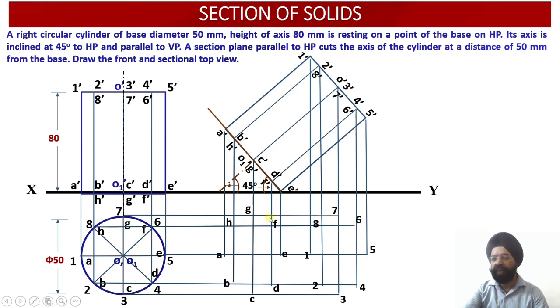So let me join. First of all, work out the two ellipses. As I have explained, since we are looking from the top, this ellipse, which corresponds to the top face, will be dark. And the ellipse I have obtained corresponding to the 8 points over here, its lower portion of the semicircle is not visible because it has been covered by the projections of the upper portion of the semicircle. So the outer ellipse will be dark and the inner ellipse will be dotted over here.